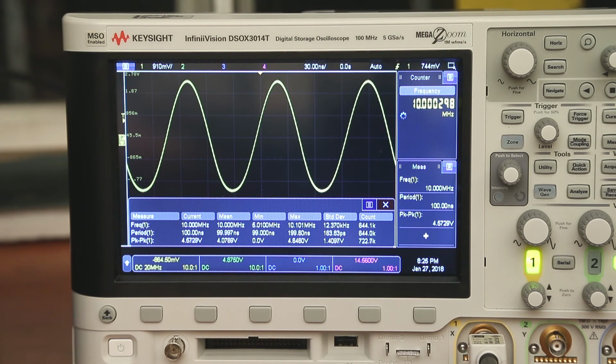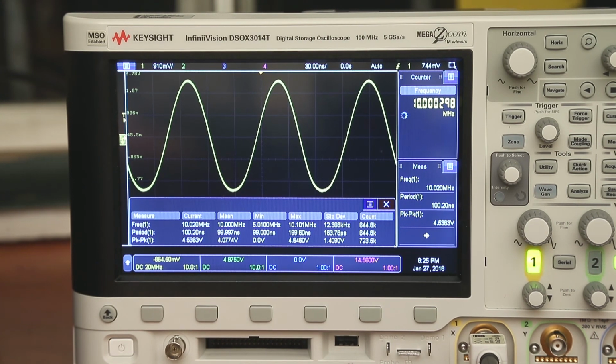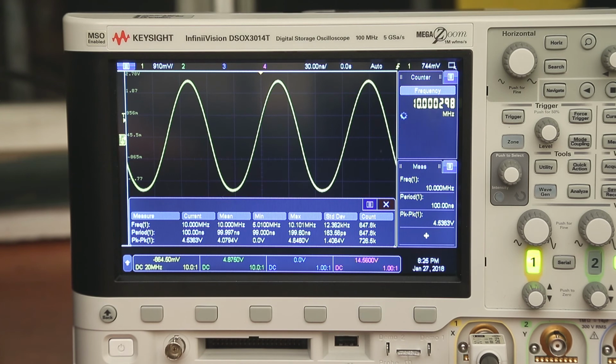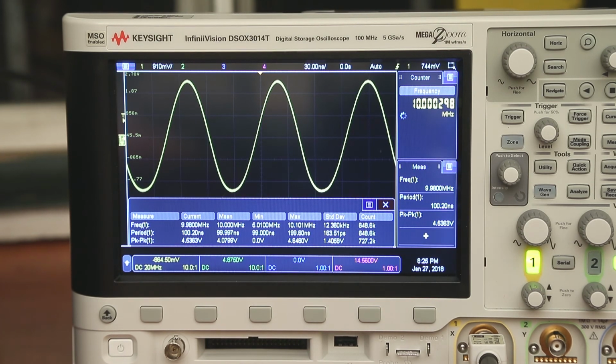Just before we do that, we're up to about 644,000 counts on the statistics, and I had the RTB running at the same time base and the same time I started it, and we're actually at 775,000. So in actual fact, the statistics on the RTB over the same time period has created more counts than the Keysight, which is again pretty impressive, and both are running I think at about 2 meg of memory, because when you alter the memory size it does affect the wave count and the statistics count on the scopes. But let's have a look at the RTB screen now.